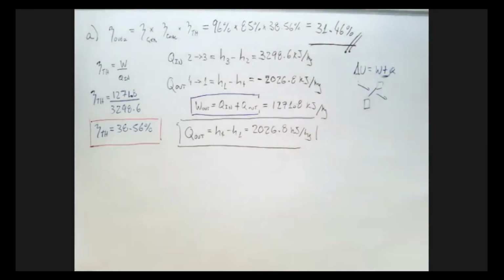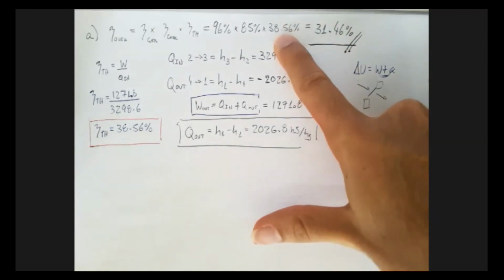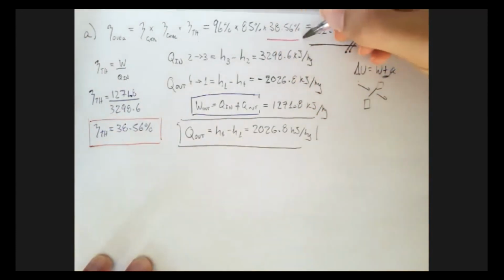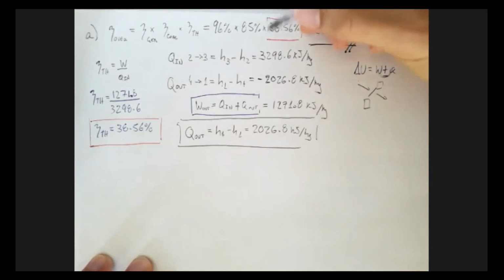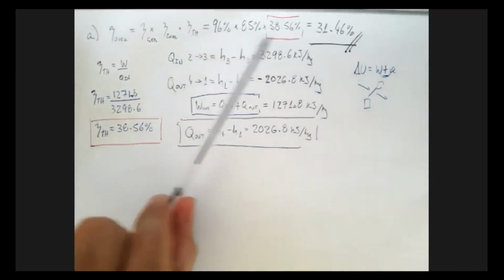Okay, so if we take a step back and think about what is happening here, we're putting in coal, and we're extracting electric energy, right? So we're using the chemical energy of the chemical bonds from the coal and transforming that into electrical energy. And out of all the coal that we put in, only about 1/3 of that energy is actually being extracted by the end of it as electrical energy. Our main bottleneck is the actual power plant cycle. So if you wanted to improve this, you can focus on this guy here, which is your main bottleneck. If you can improve this, everything else improves. Obviously, if you can get small improvements on all of them, it's even better.